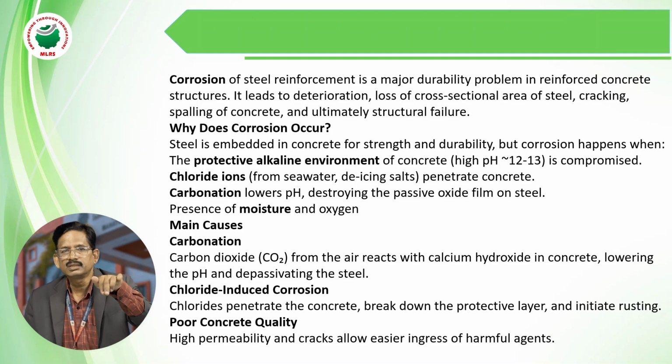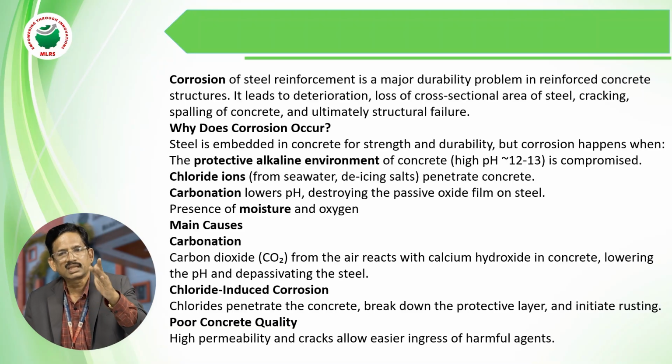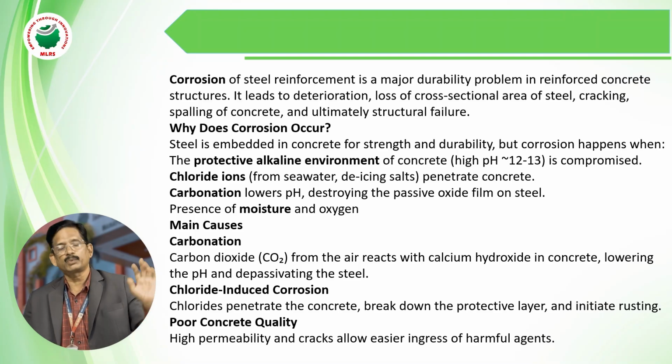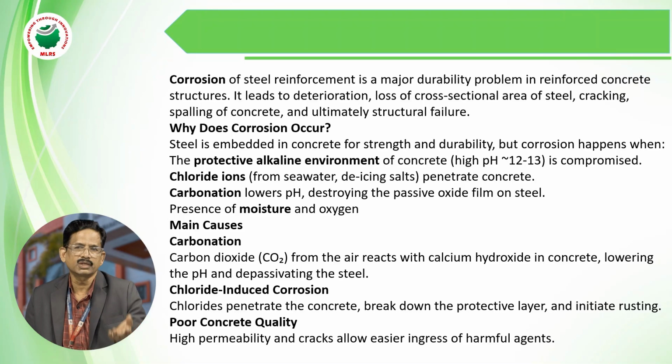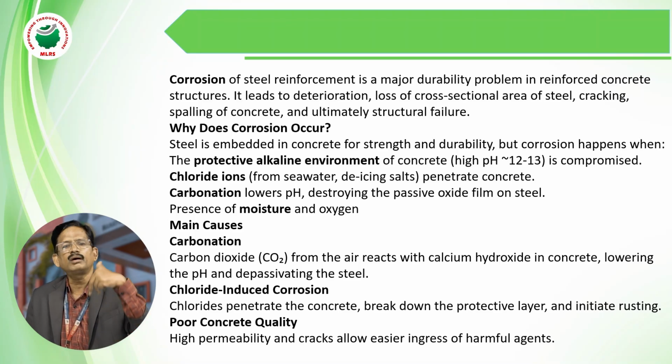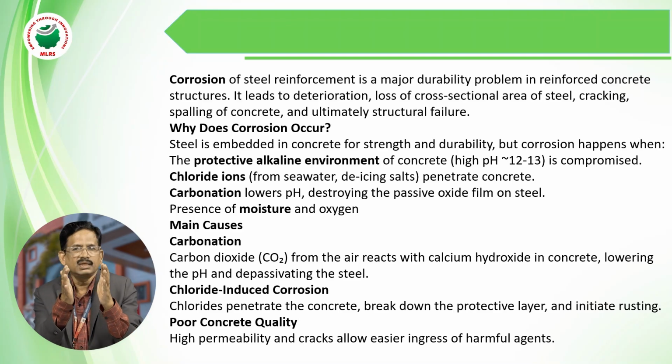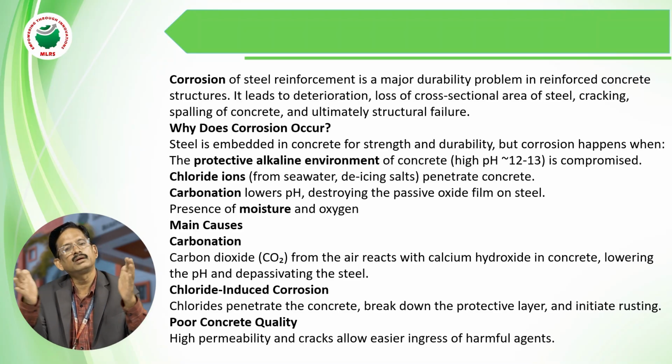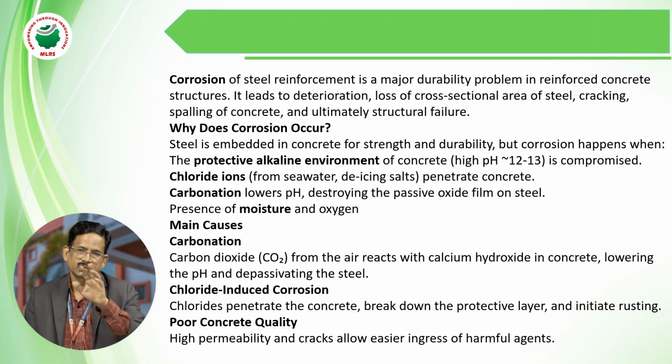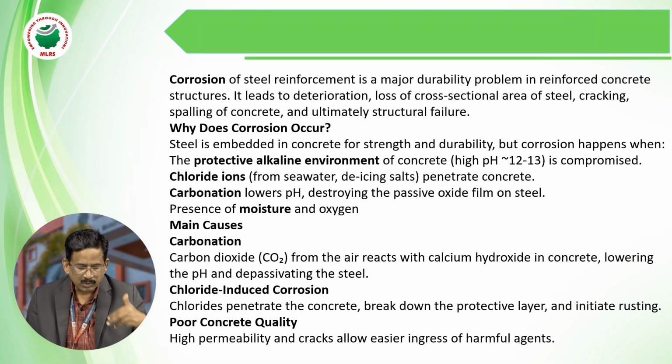That's why in the concrete lab we test the cubes for strength, workability and mechanical properties, as well as durability properties. Durability properties means acid resistance, the rapid chloride permeability test, or the carbonation test. These are the tests we do to find out whether the durability of the concrete is good or bad. So, we design structures for the strength aspect as well as the durability aspect.